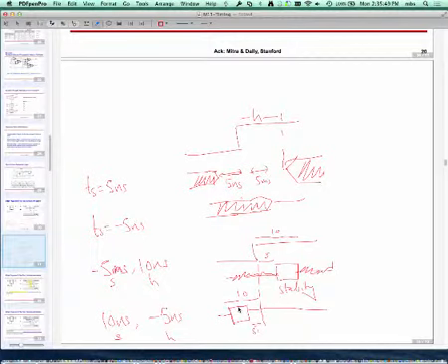How is it going to read into the future? Firstly, it's actually not reading. What is happening is that in this particular case, the circuit probably has some delays in it on the data line. So by the time it reaches the place where the clock is doing its job, this data would have been delayed. So let's imagine I take this data line and I make it go through a wire which has a delay of 10 nanoseconds before the clock looks at it.